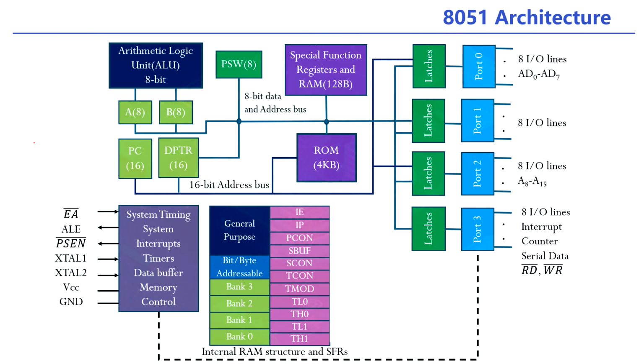If you observe here, already we know that the 8051 supports program memory as well as data memory. Already you know that this program memory is accessed through PSEN bar. That means the PSEN bar is connected to RD bar of 64 kilobytes of external memory.